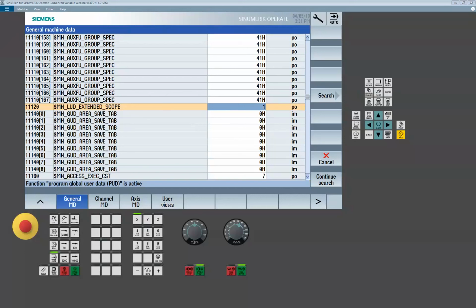Is there a benefit to using the STOPRE command in this sub? So STOPRE stops our look ahead. You do get into some cases, especially in these short routines, where the look ahead may be displaying something different than you're expecting. The routine may still function okay, but you may get some weird behavior. Say I'm telling it to cancel an offset, but I see the offset being displayed even though it's not being used. It might be the look ahead reissuing it.